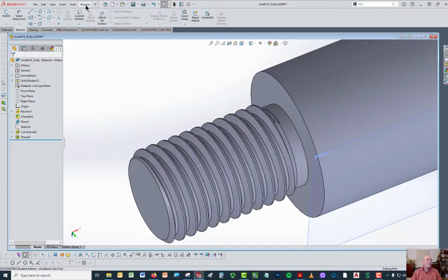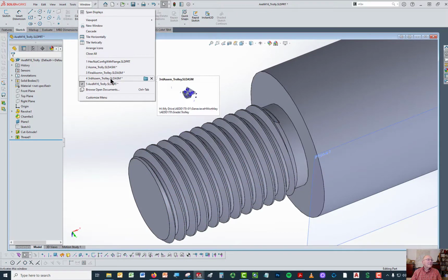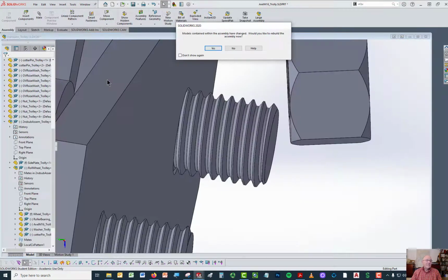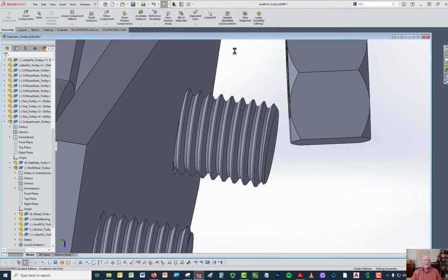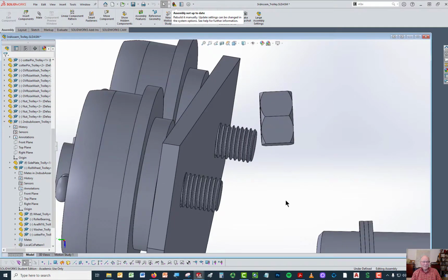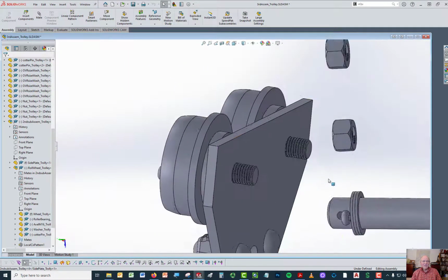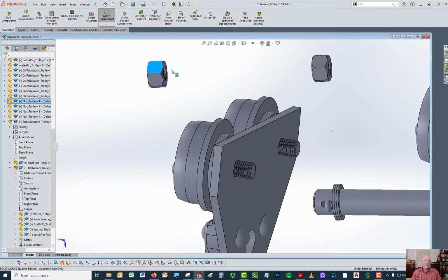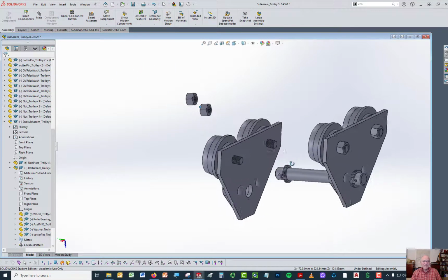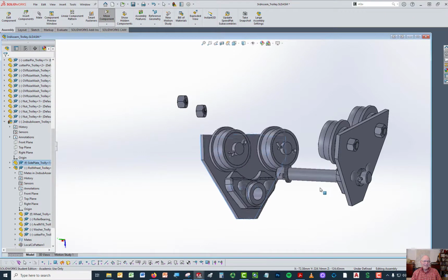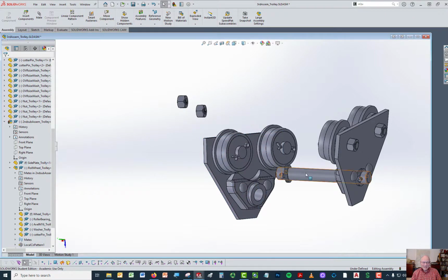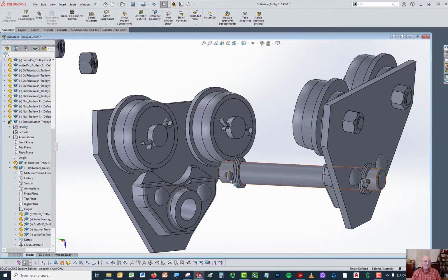So now if I go back to the third level assembly, which I've got right here, now I've gotten rid of that little step. Now that's not the problem with this assembly, it's just a problem. Now those nuts should be put on there, but that's easily done. I'm just going to move them out of the way because what I'm concerned about right now is putting this on in the right orientation so it sits on that axle and then constraining it the same way I did this with real world constraints and then see what the position is.